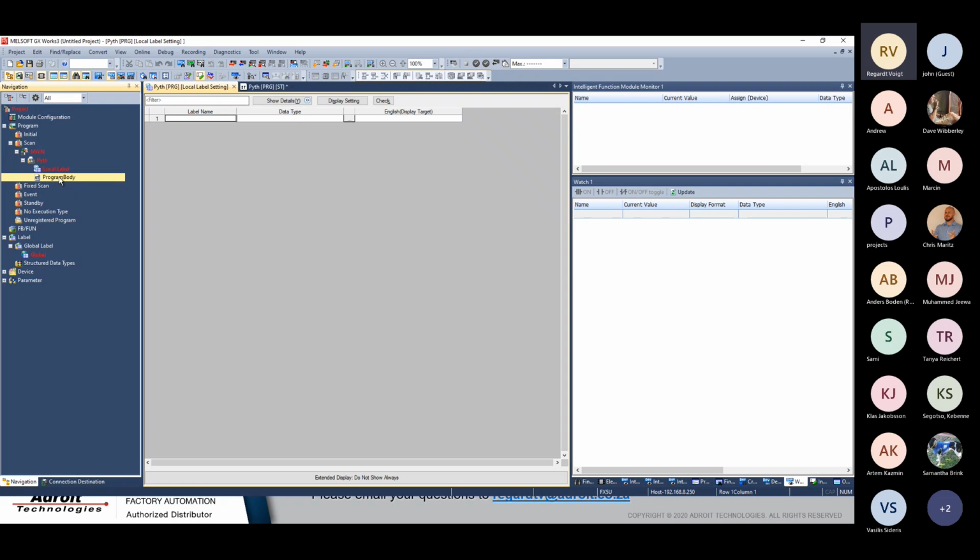However, if it's an item that will be used externally, like SCADA, GOTs, VFDs, servers, or another PLC, for instance, then you're going to have to use a global variable, because this will allow you to assign a register to each variable. Also optional, but you can assign it.